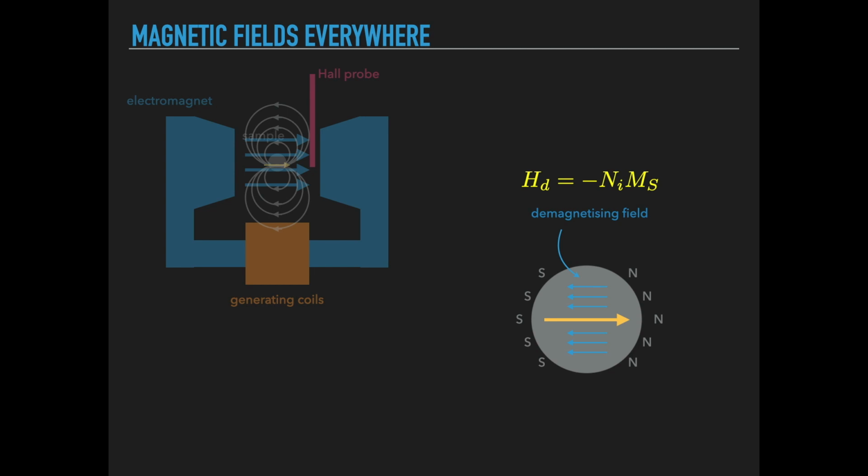Generally speaking, the demagnetizing field is proportional to the saturation magnetization of the material through a coefficient that depends on the sample shape and on the direction of the magnetic field with respect to the shape of the sample. However, this expression is correct only in the case of ellipsoidal samples and in the case they are completely saturated. If that is not the condition of your sample, this expression is only approximate, and an exact calculation of the demagnetizing field is not possible. Numerical methods are required for each applied magnetic field value, and therefore for each magnetization value assumed by the sample in that condition to calculate the demagnetizing field.